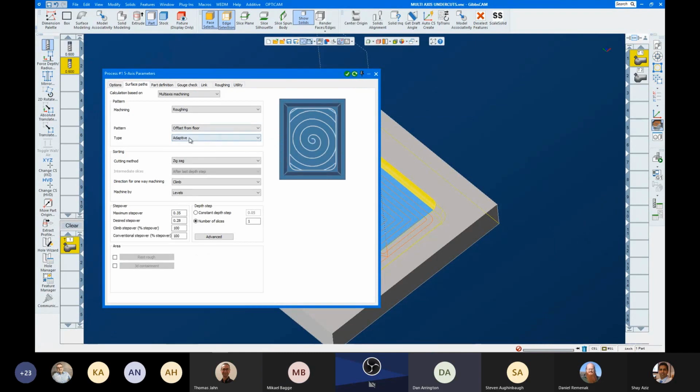So when I use this, if it's a decent sized part, I'll set the step overs really wide and loosen up some of the tolerances just so I can see the toolpath to make sure I didn't miss anything. But you're right, that is a huge drawback to this. Yeah, keep bashing them, I guess that's a good idea.